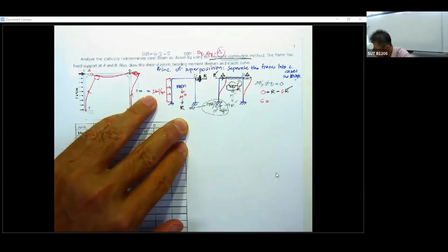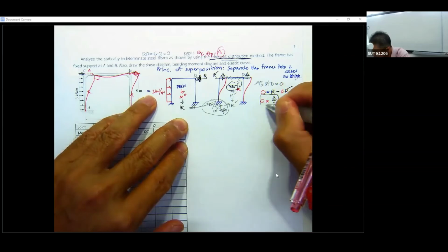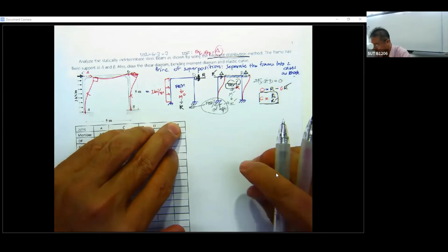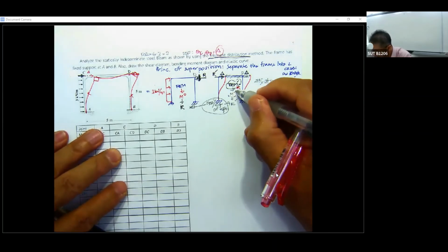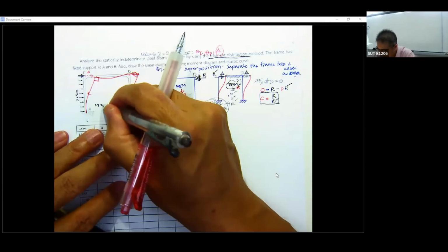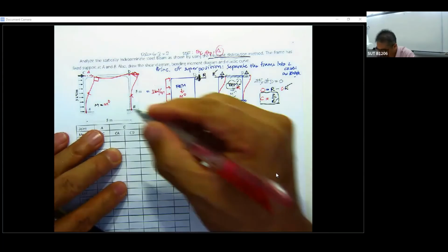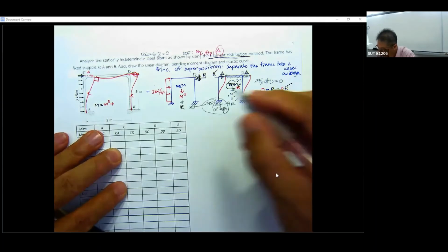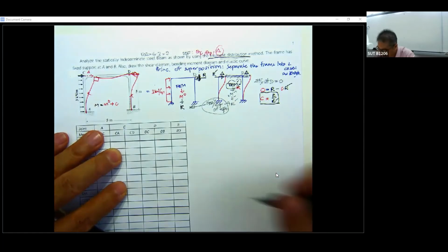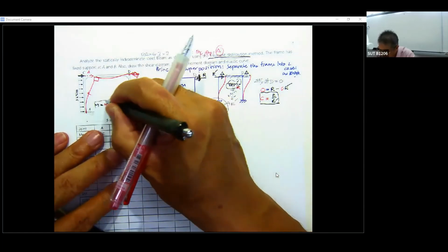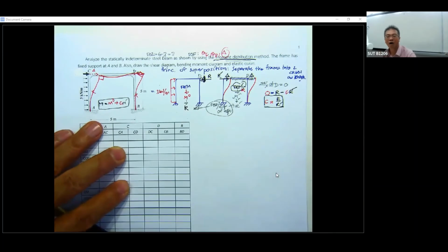So C is going to be R divided by R prime, and we will determine this for computation. First you use it to adjust this, and then the moment here is going to be equal to moment M super knot plus C times M prime over here, and then you get this end moment for the frame that we are considering.